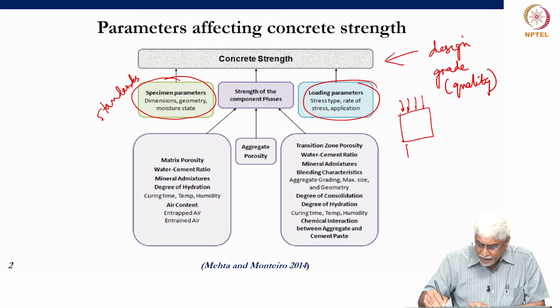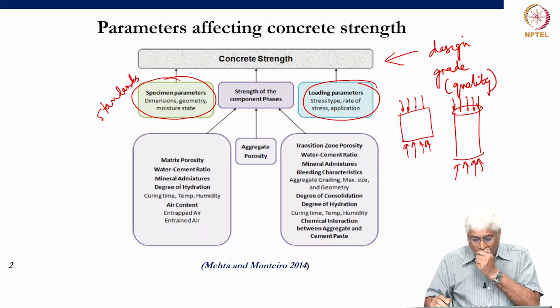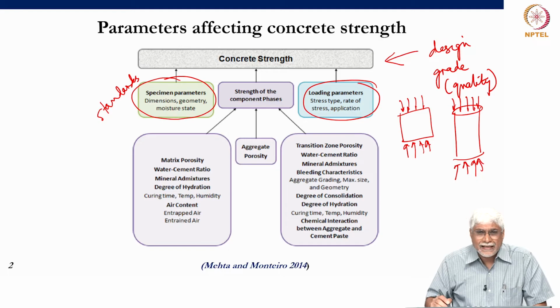So, you have a cube or a cylinder under uniaxial compressive stresses. This is how the specimen is loaded at a certain stress. Generally, when we do a test under what we call quasi-static conditions, the failure occurs in about 3 minutes.